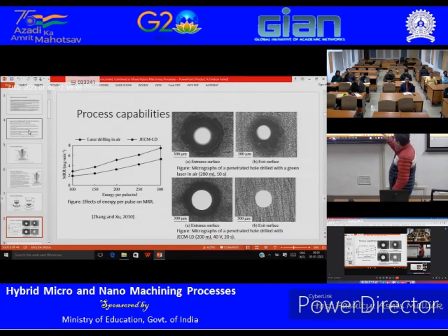And if you look at the surface and the profile accuracy of the machined micro holes, this is the entrance side, this is the exit side, just with the laser in the air, okay? And you see both the entrance side and exit side have a significant heat affected zone, and also the profile accuracy is not very sharp. You see the profile is very blurred, and you can see the taper, right? You can really see the taper.